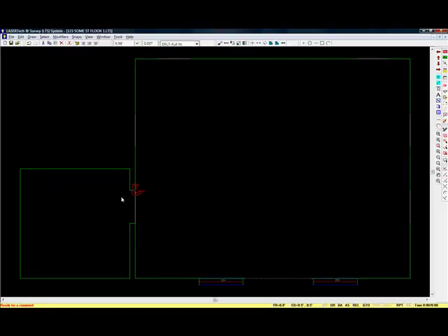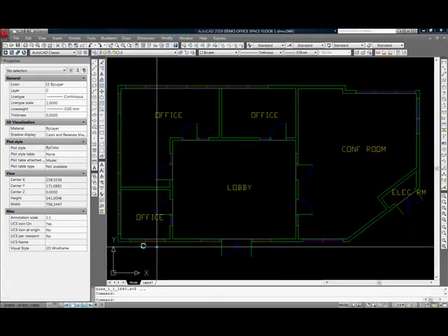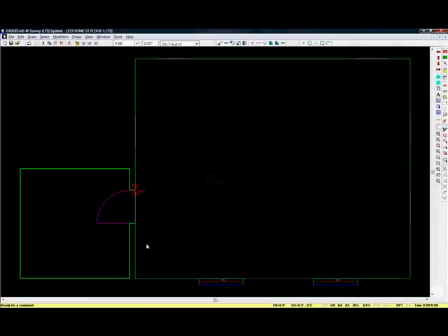Now we want to put a door in. The door swings in here, so we have a door tool. And it just says pick the hinge point, pick the striker point, which side is the door on. We click inside the room, and it places the door. Now let's say there's, as you can see over here, a couple of windows here. So now we have 2 windows. So we're going to place 2 windows in this wall.